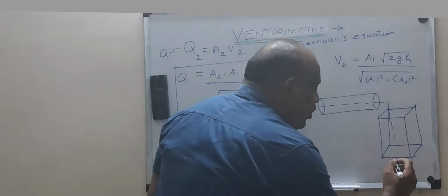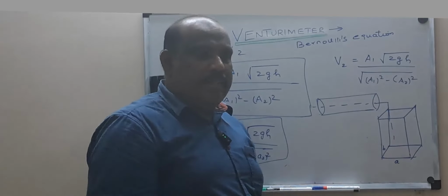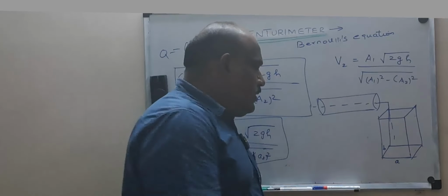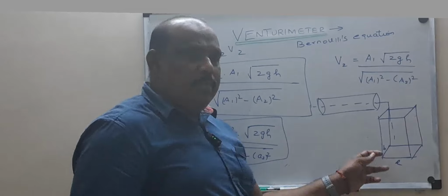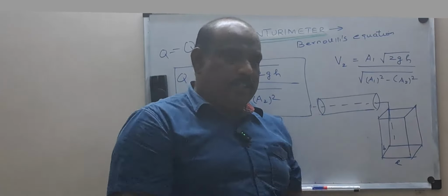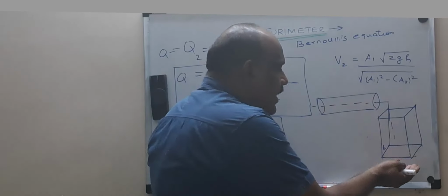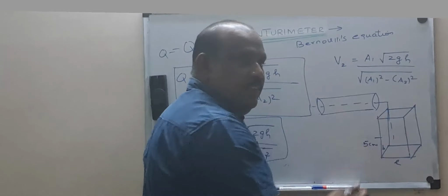Let us say you know the base area of the tank. Let it be rectangular, so length into breadth. Instead of A and B, let us use L and B because we already have A. Now use a stopwatch, or take your mobile phone, and allow the water to rise, say, 5 centimeters from the ground.